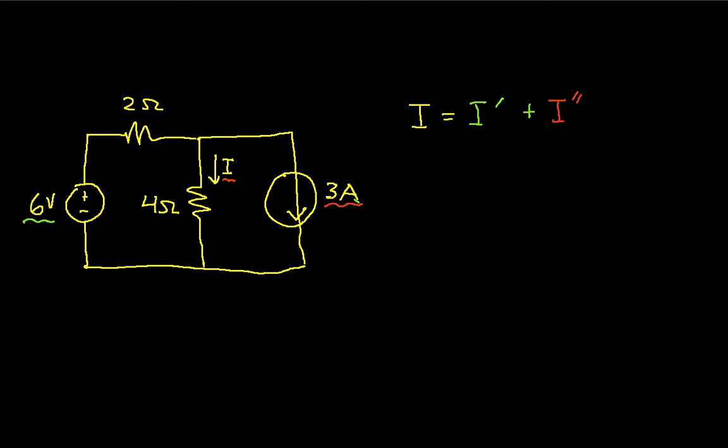So with that introduction, let's actually try to solve this circuit. Again, what we would like to know is what the value for I is, and we'll just go ahead and try and solve it. The first thing we need to do to apply superposition is choose one independent source. We'll choose this 6-volt source as the source we're going to use, and then everything else goes away.